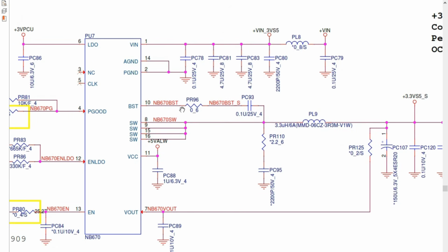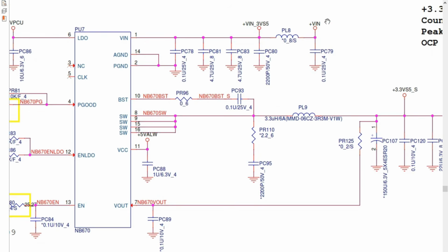So the first input is the VIN, the working power for this IC, as you can see. The VIN basically is about 19 volts. You can find some motherboards with 20 volt, 15 volt, etc. But usually the VIN for laptop motherboards is about 19 volts. So let's assume that the VIN is 19 volt. The 19 volt will pass through this inductor, as you can see.